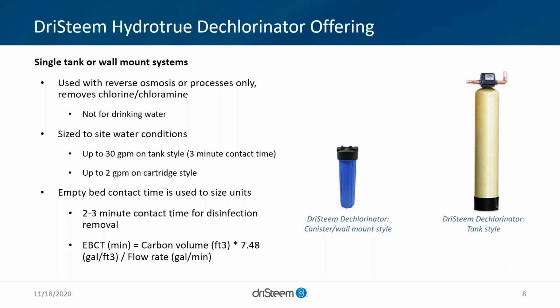But again, it's a control valve, and activated carbon is filled inside there. Some different flow rate information. The cartridge style is great for low flow rates. The thing we're really looking for is contact time. I didn't put this exact info in the presentation, but I believe Pentair water talks about 5 grams of activated carbon equaling 32,000 square feet of surface area. So this carbon, as you break it down, becomes more porous. But along with that, we do need contact time to effectively remove and have that reaction occur.